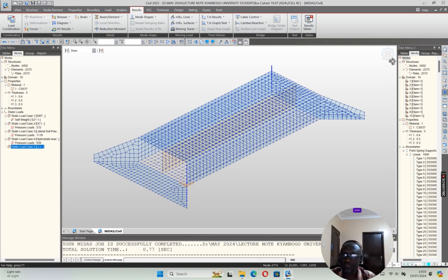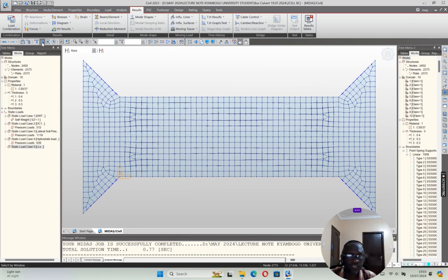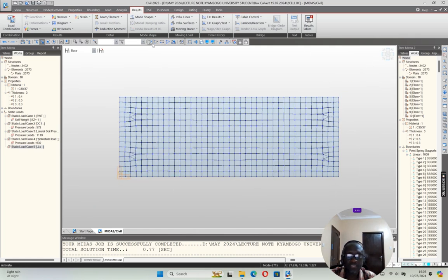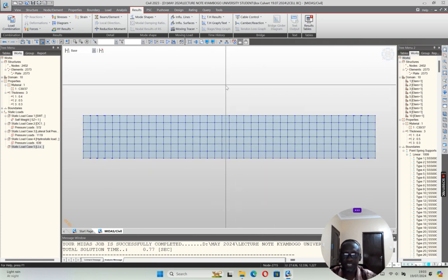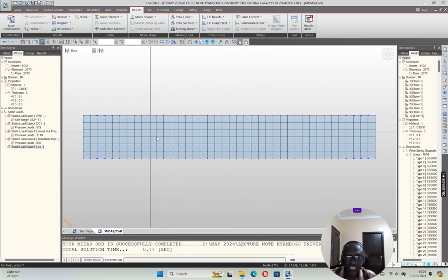You can apply it, but make sure you know the extent of the wall. This is the wall extent, in line with the traffic. The center line of the traffic could be here, and then you have your 5 meter, 5 meter, 10. So the surcharge would be in the middle, concentrating within, what would you call it, within the carriageway.